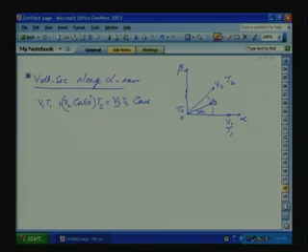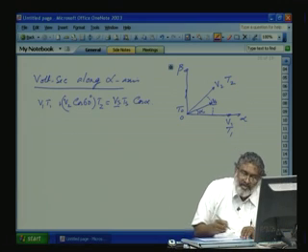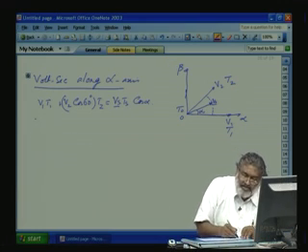Now, what do we want to find out? The sampling period is fixed by us, but T1 and T2 we have to find out, and they depend on the Vs magnitude and the angle. So we have to find T1 and T2 for a particular Vs, which has a particular magnitude as well as angle. We require two equations. The next equation we can get along the beta axis.